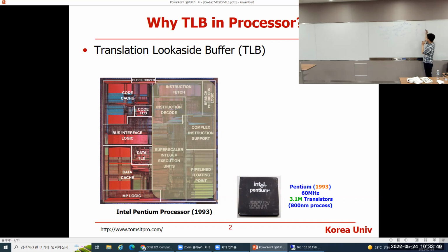So the CPU is reading these two data and separates the sign bit, exponent bit, and mantissa. Then for this arithmetic operation, what do you have to do? The exponents should be equal. Then you can do the addition. So a very complex operation is happening inside the CPU.